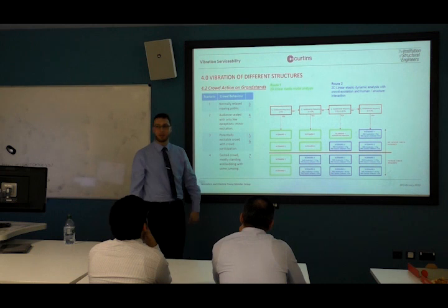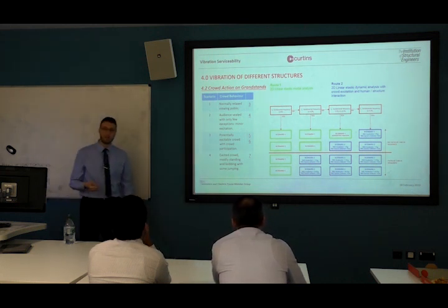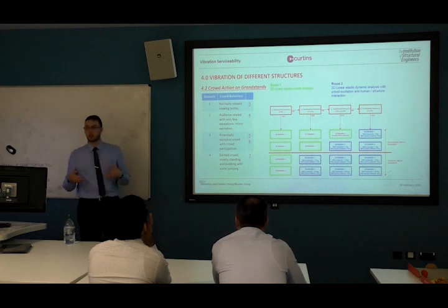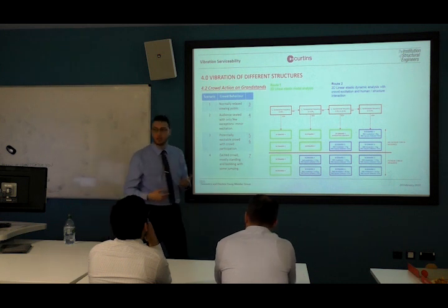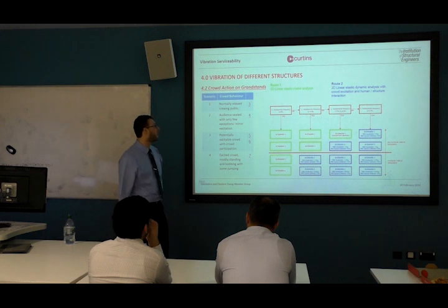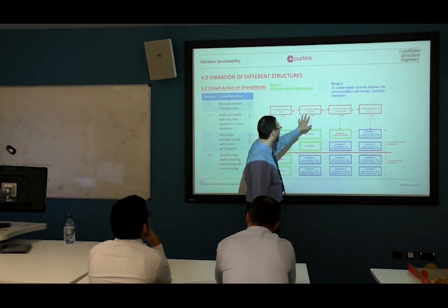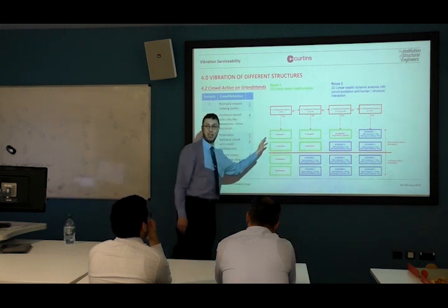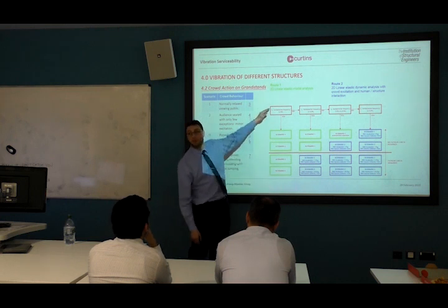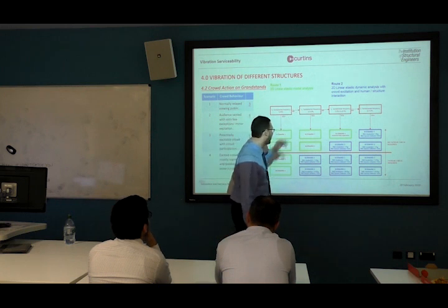And the thinking behind it is that when you are bobbing and jumping, you're not going to excite your structure at resonance if the structure has frequency more than 6 Hz. And then we move on. It's very difficult to find a grandstand having frequency higher than 6. So okay, is it greater than 3.5?